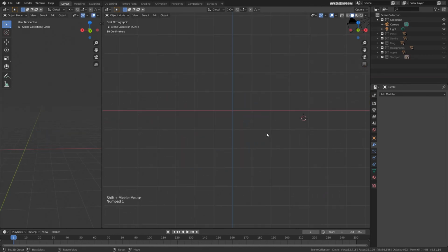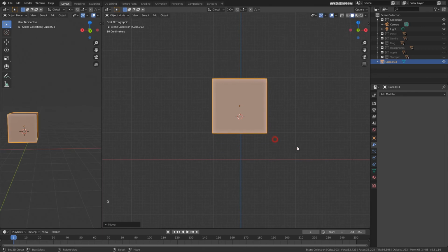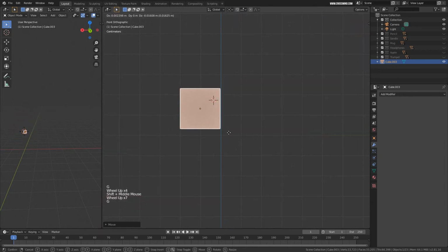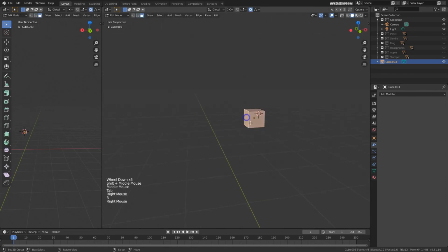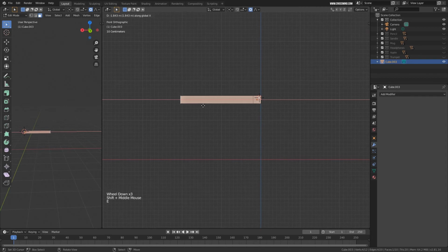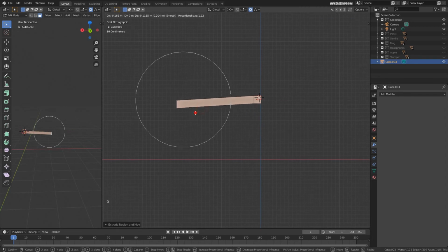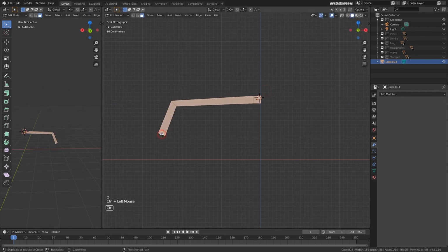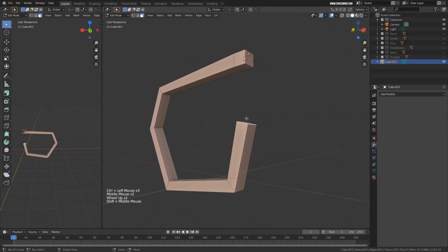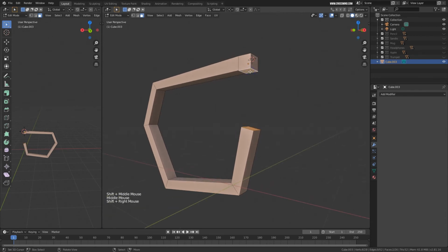Now I'm going to create glasses. I'll bring a cube over here and place it right here and start shaping the border, the outer frame of the glasses. Okay, so first I'll create one simple extrusion and bring it over here. Yeah, so I'll control click over here, control click over here, and create another one, and maybe select these two faces and delete.